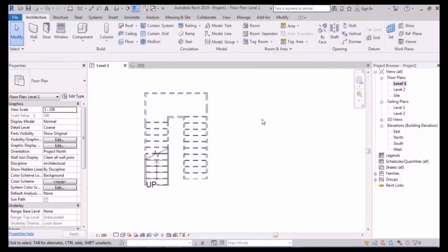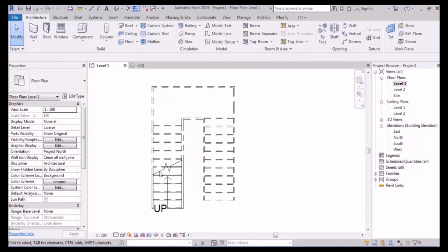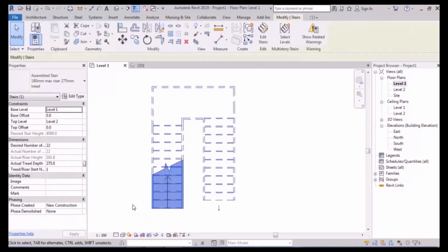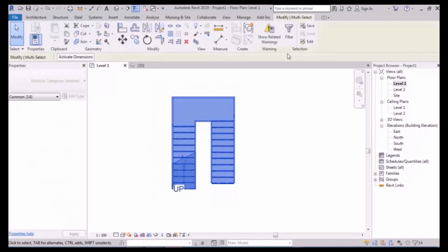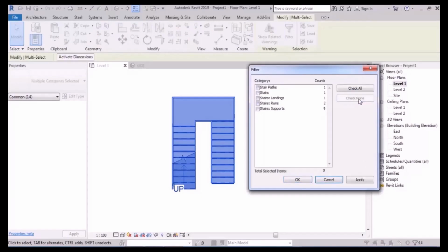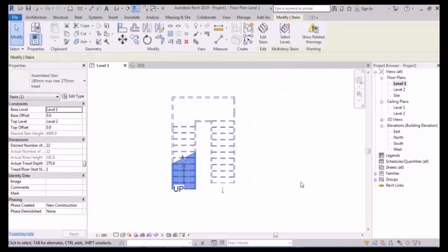So to make sure you can select your stairs quickly and easily, my advice is to click on it before this arrow sign. Or you can open a box and then go to filters, and in filter, select only the stairs. This is possible too, but why would we do that?